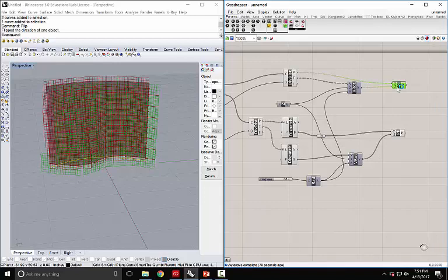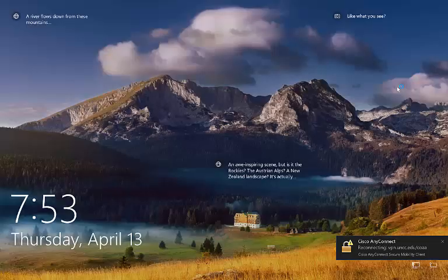So the first thing that I'm going to put in here is to set an expression, which is going to be x divided by 2. And I'm going to do this for all three of the different inputs. Because our brick values are the full brick size, we're going to use this expression to ensure that we actually get bricks that aren't twice the size of what we want.